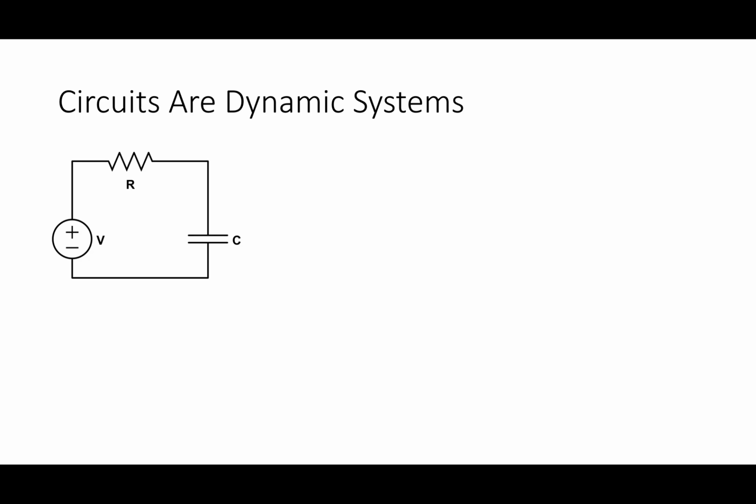Just resistances. Yeah, and so what makes that system with just resistance static? If I just had two R's like this instead of an R and a C, what makes that a static system? The voltage and current relationships aren't changing, like derivatives or integrals. Yeah, they're not changing as a function of time, basically. As soon as you turn things on at time t equal to 0, the currents and voltages are all steady.